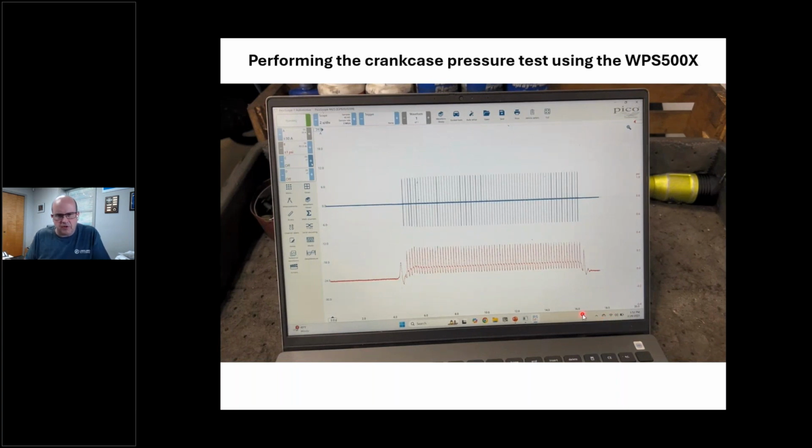That's all I ran that truck. You see, this is where I started up. That's number 1 injector, and this is my crankcase pressure. So if I look in here, I didn't run this thing, 12 seconds? 12 seconds. Remember, it's diagnosed in 15 minutes. I got what I need here in 12 seconds. I mean, yeah, I had a little bit of setup time, but everything I need is right here.